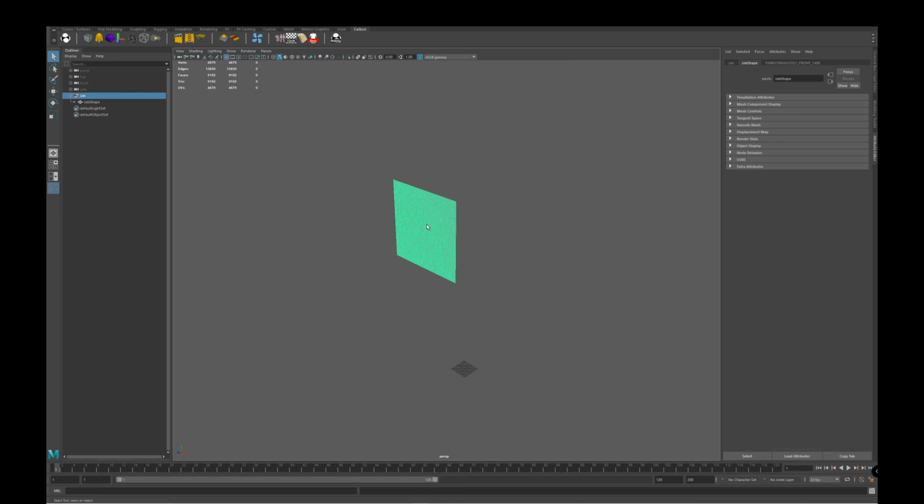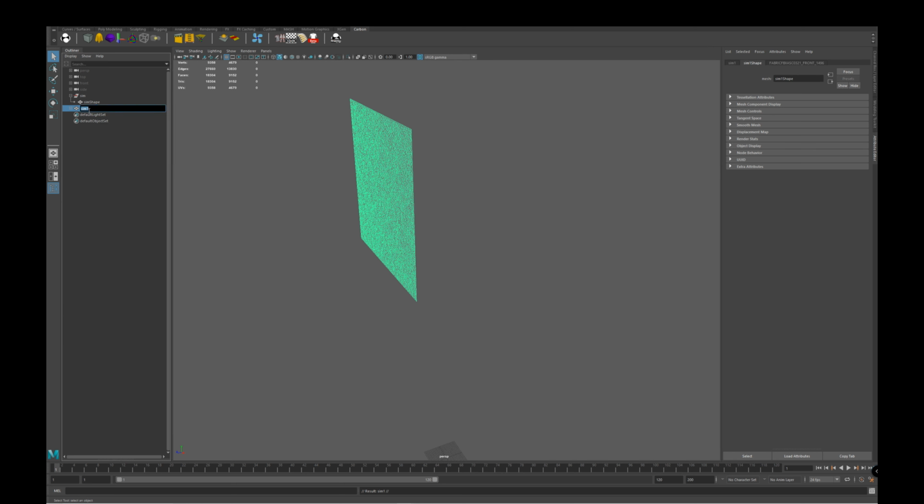Here we have the thin sim mesh, and to make this video production faster, it's just got 9,000 triangles. But the workflow is the same for a 9K, 90K or 500K simulation mesh. The first thing we're going to do is to duplicate the simulation mesh, as we want to keep a reference copy in the import position for when we later map it to the render mesh. We are going to drop this vertical cloth onto the ground plane and then pull it around.